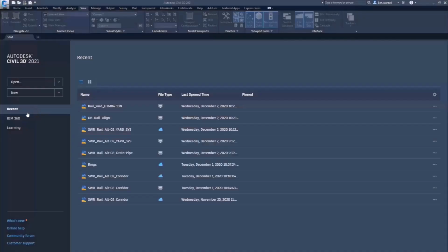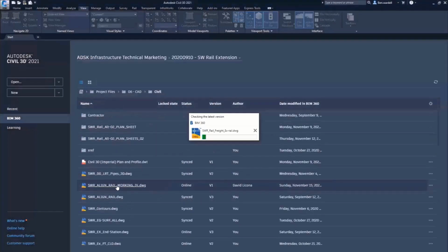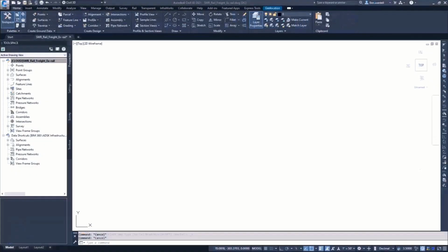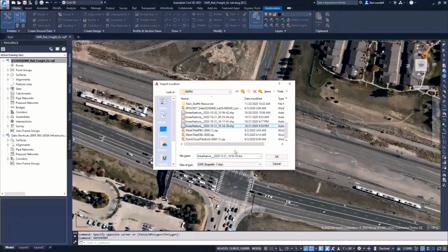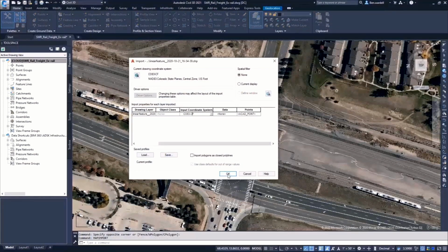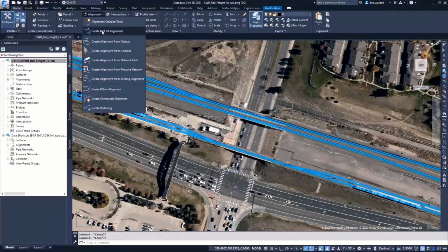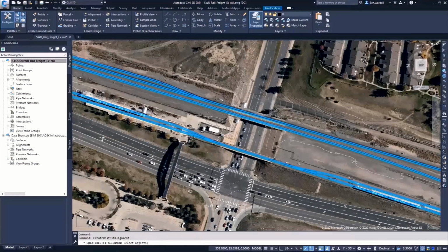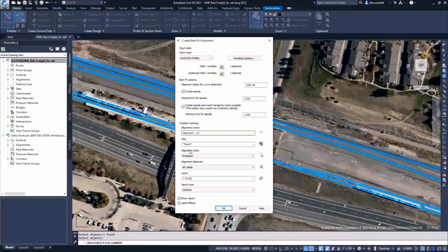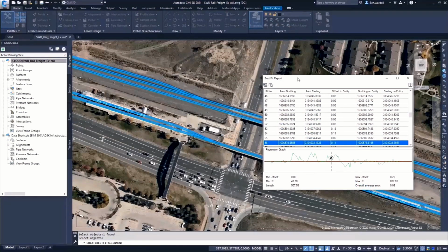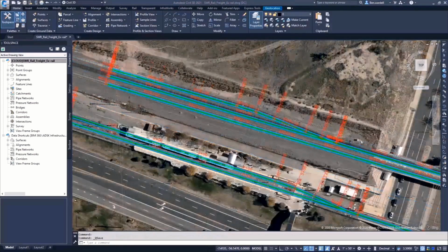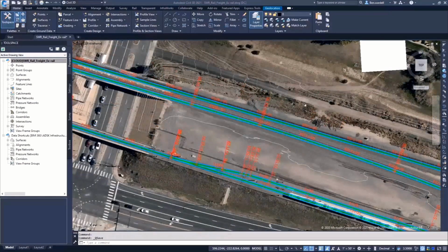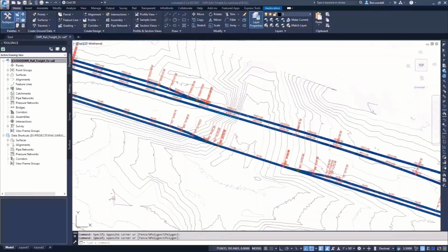So then in Civil 3D, we can utilize this data that we created in InfoWorks from the point cloud, where we can generate the surface from those transverse lines, and the 3D lines that we extracted earlier will act as a basis for the existing rail alignments. We can run a regression analysis to determine the location of the existing rail centerline alignments. These alignments are fully dynamic and can be revised as needed. And we could create a profile in this same way since these rail lines are three-dimensional.